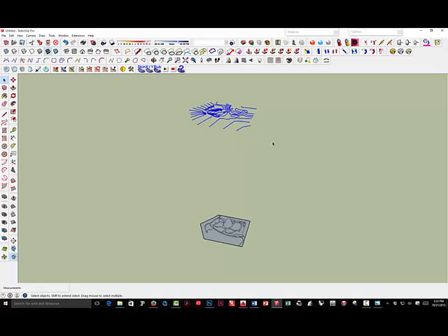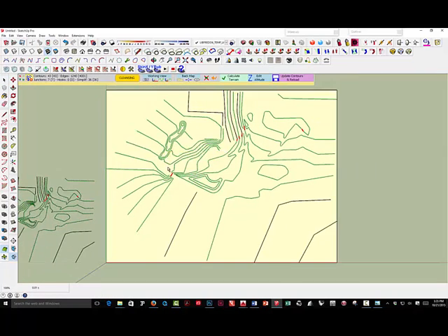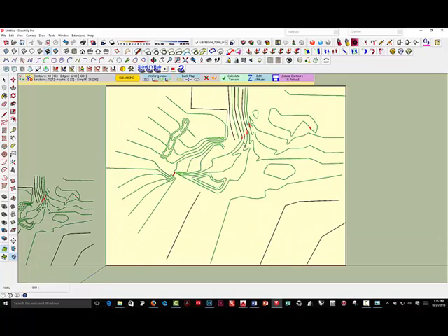Okay, select it all. And that Topo Shaper icon is the one you've been moving around that has a little green icon. The terrain from contours is SketchUp's built-in, but I want you to use Topo Shaper. Then you select the contours and click on it, and it gives you this little map. And it sees gaps in the contours and tries to connect them.